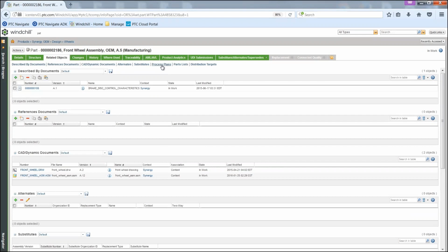What you can do is you can see in the parentheses at the top, you're going to be creating specific BOMs for the different departments. As I said before, manufacturing is the one we're going to be working with today. You can see it in parentheses at the top. What you can also do is just set this as the default for users or different roles. So let's say you have people from manufacturing that are going to be working in here. You could just have this BOM as the BOM that they're going to see by default whenever they log in and search for a part.